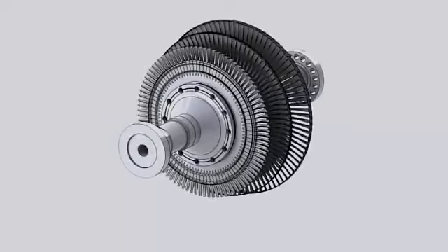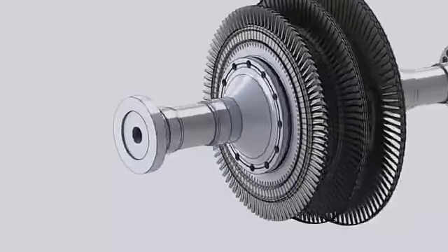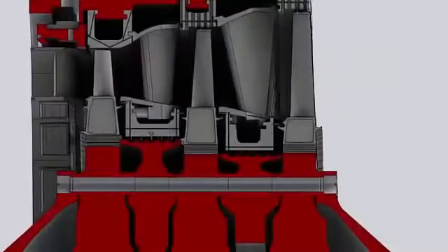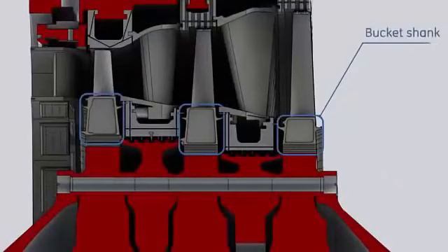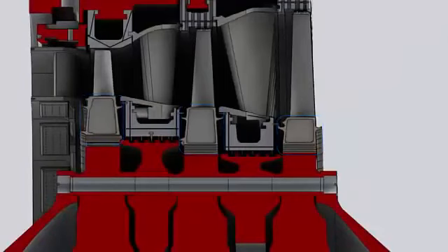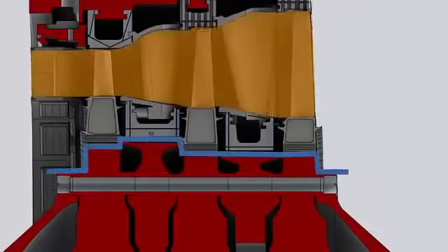The turbine rotor must be maintained at reasonable operating temperature to assure a longer turbine service life. For this purpose, bucket vanes are not directly attached to the dovetail. Instead, they are connected to their dovetails by means of shanks. These shanks locate the bucket to wheel attachment at a significant distance from the hot gases. Combined with the diaphragm segments, this arrangement isolates the rotor away from the hot gases flow.